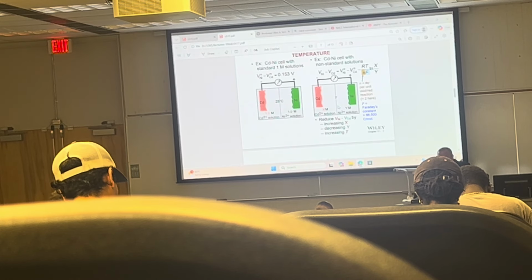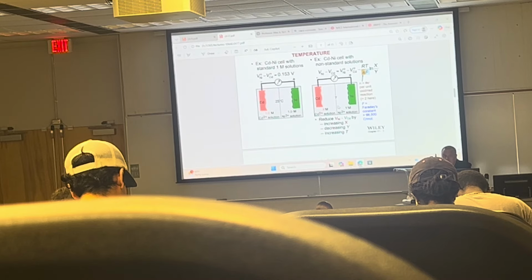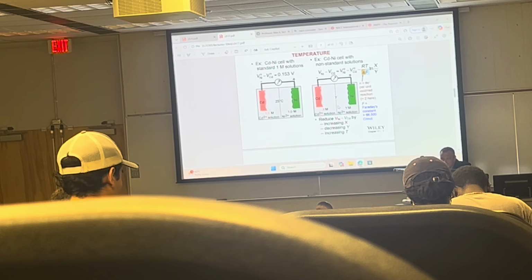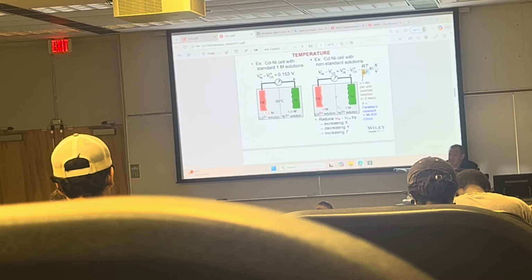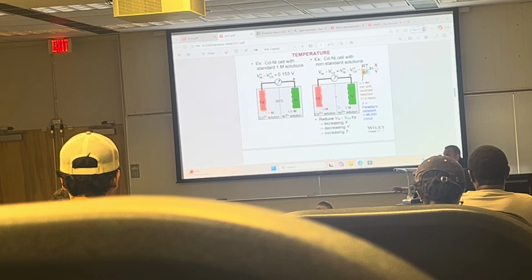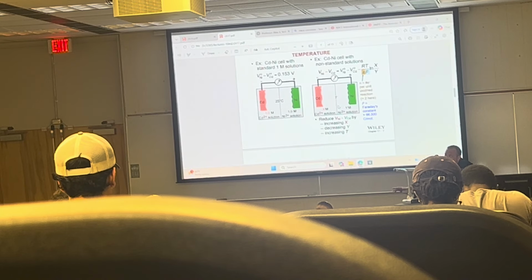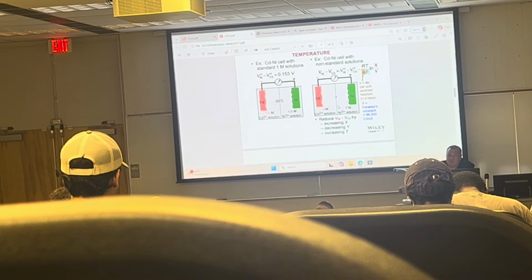There's another rule that if you need to do corrosion mitigation, then for $1 spent for corrosion prevention, you would spend $100 with mitigation. What does that mean? Let's say somebody painted this wall, and there's something wrong with the application, or there's something wrong with the paint, or the substrate was dirty, and this paint starts to peel, or it locally starts to delaminate, or there's any other problem.